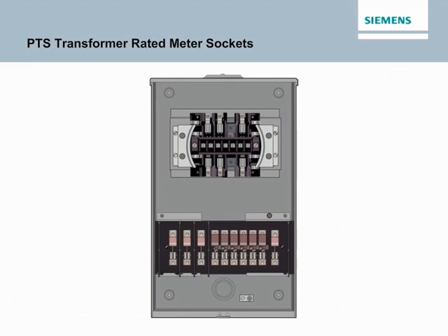For larger applications where it's necessary to meter loads which have a continuous current above 320 amps and/or when the applied voltage is 3-phase, 480-volt, transformer-rated watt-hour meters are often used. These meters are also used in off-peak metering applications where the utility controls the power applied to a device to limit energy consumption during peak demand periods.